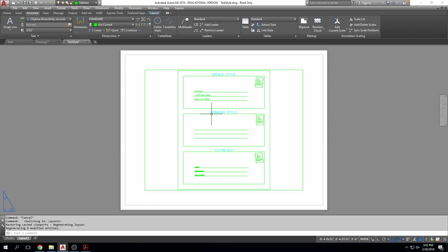So you're going to create an annotative dimension type. You are going to set your annotative scale in model space for your dimensions. And then when you go to print in paper space, the viewport that you create will be specific to the scale of your dimension, right? So all of these same things that we're talking about with text are doing double duty on dimensions as well. All right, I have my page here, right? We're getting some good practice doing page sizes in paper space.